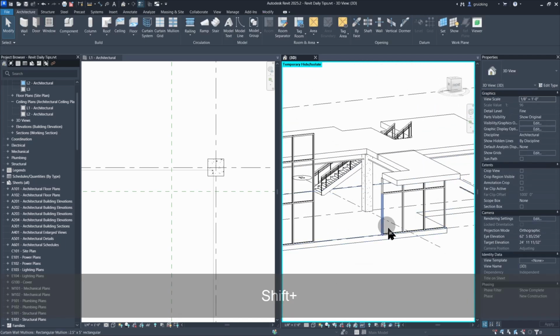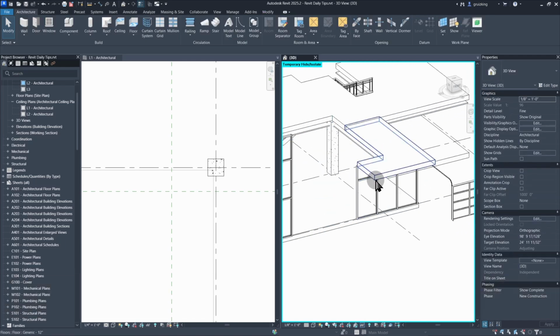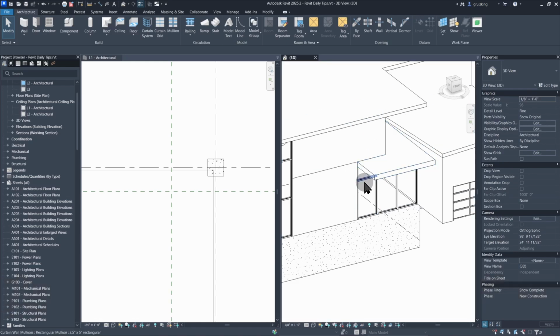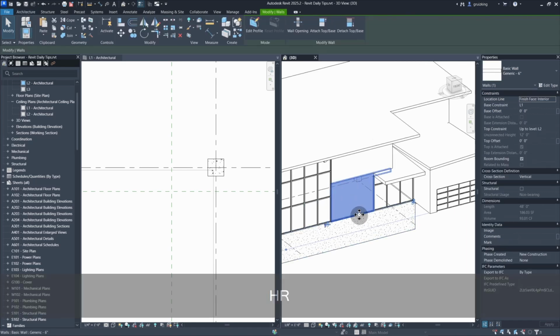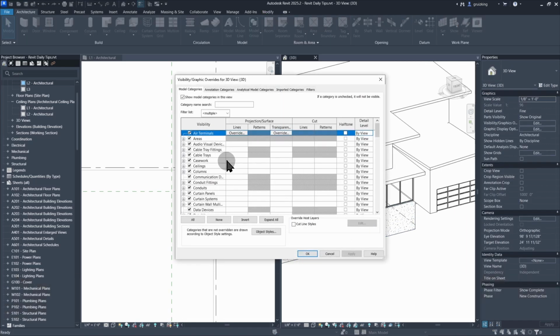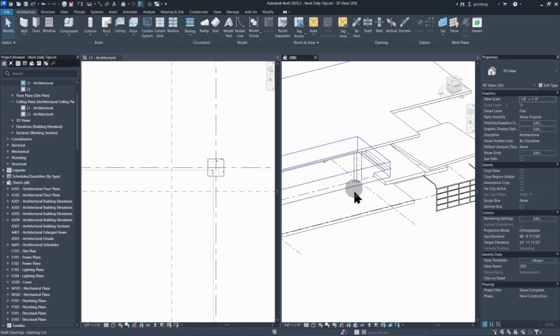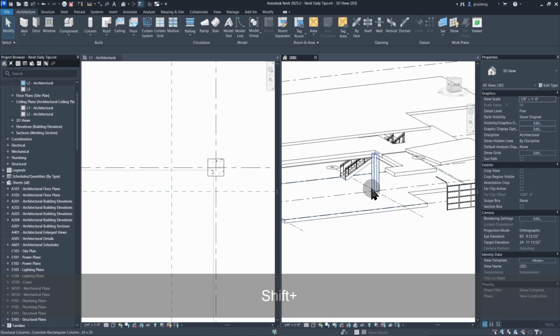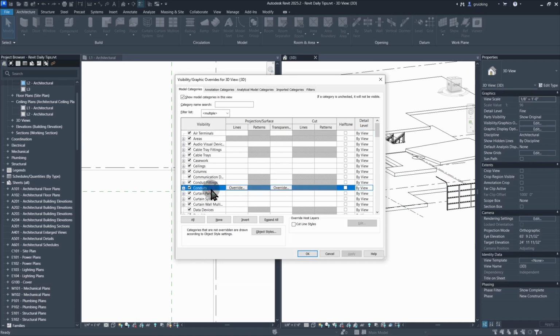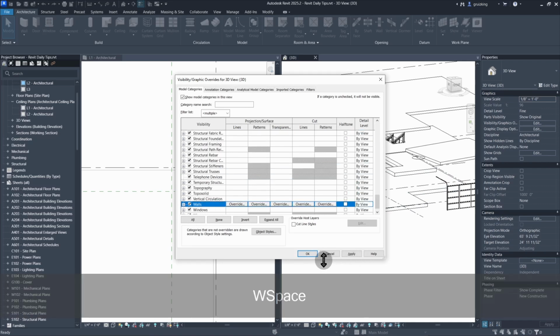Now let's look at the beams. So this view is sort of already set up. I'm going to reset it. So something that's really useful inside of Revit, it's just right here, these glasses. All right, this is your temporary hide and isolate. So it's nice because you don't have to go into visibility graphics, turn off your walls, and then have to remember to turn them back on afterwards. I have to go do that. Walls, turn it back on.